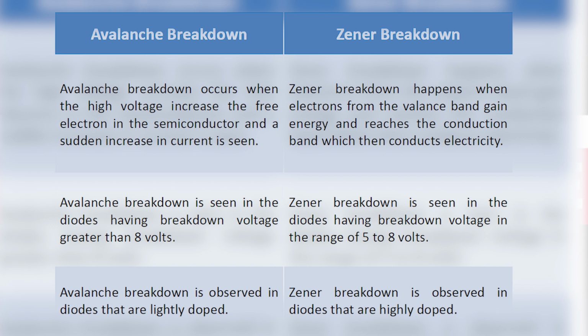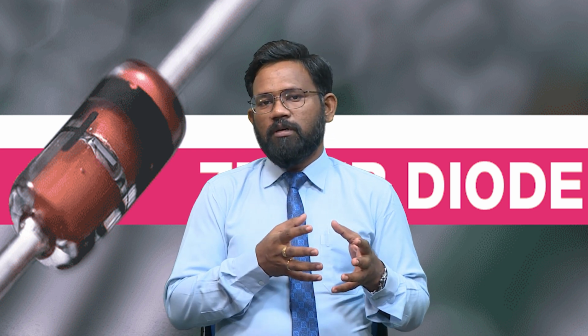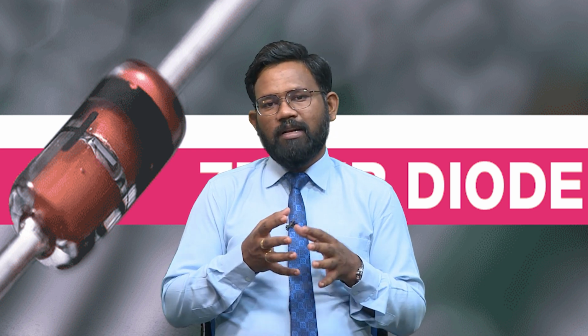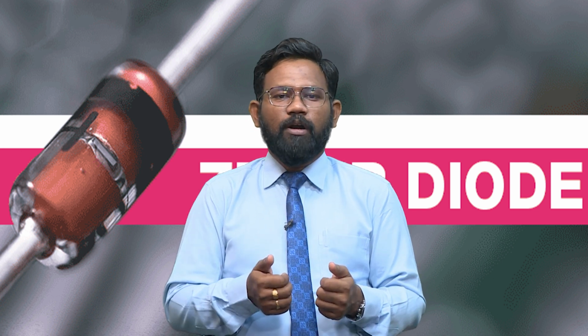The next difference is that avalanche breakdown is observed in diodes that are lightly doped, whereas Zener breakdown is observed in diodes which are heavily doped. So this is the main difference between the normal p-n junction diode and the Zener diode, and this makes the difference in the breakdown also.